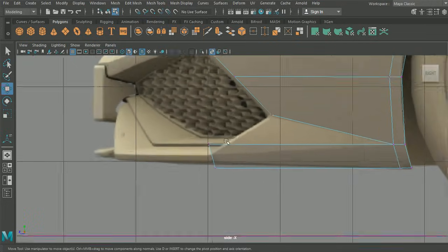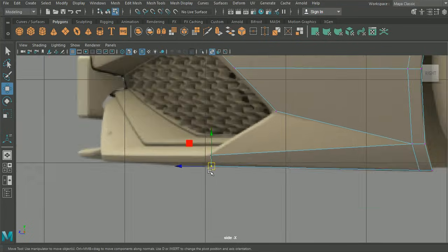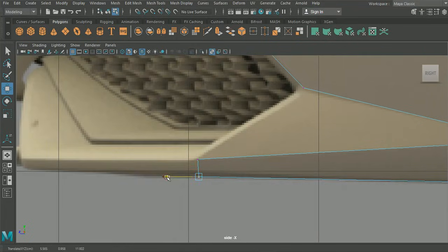And what we're going to want to do is position those nicely along this edge here. So we can see this bottom section doesn't have an edge. Because we're going to want to follow this around again, we can just keep this nice and straight. That will allow us then to extrude this section around this edge here. To make sure these are nice and straight, we can use the scale tool here with both points selected. We can just scale in just to make sure that it's nice and straight there.